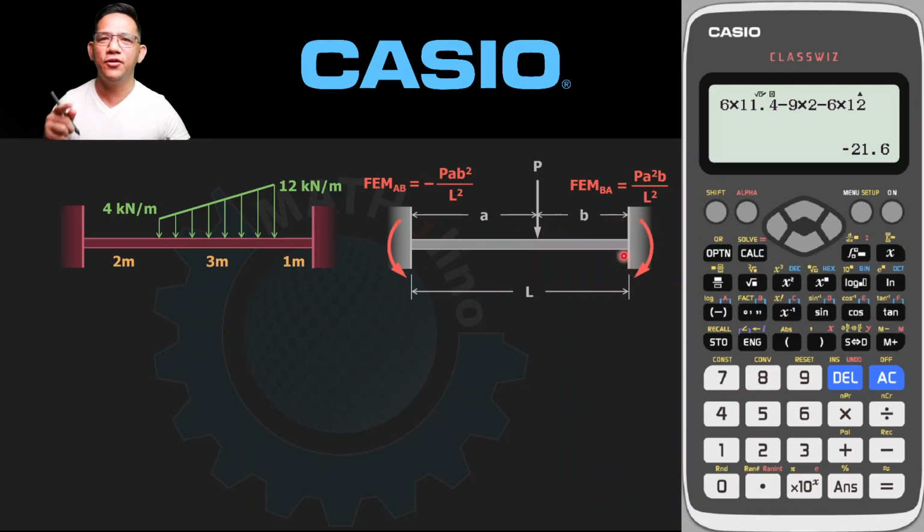That is only an assumption, which means that we need to be consistent up to the point of interpretation for these assumptions of the rotation of our angle. Now, we are going to model this for the fixed end moment in our actual beam. We are going to model this equation with a strip again. So we are going to select the coordinates of our XY plane. This is our origin. Now, create again a strip with area ydx, and that will serve as our P ydx.